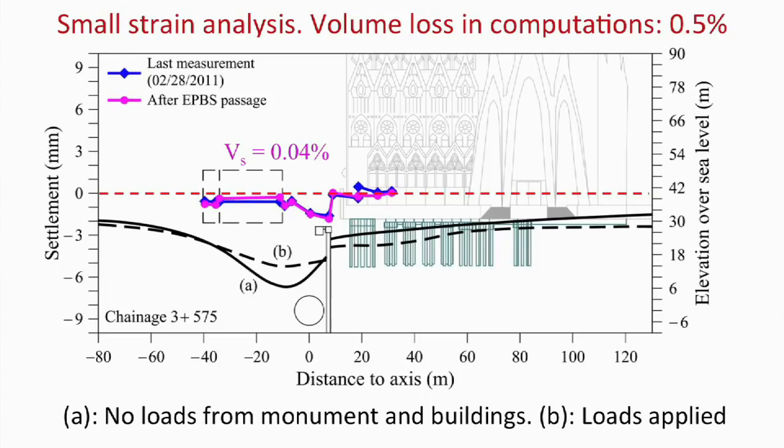Now, as a rough idea, with these machines, 70% or so of the settlement comes almost immediately as the built tunnel leaves the protection of the shield. Then you get 70% or so, even more sometimes. Now, 20% or so, or maybe more, or around that, comes from the initial excavation, from the passage of the machine, etc. And then a little bit later on, and this, of course, takes place in time, but is a small amount.